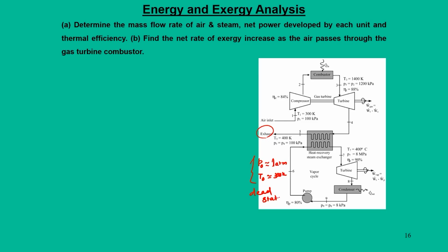Now, when you perform this exergy analysis, the picture will be clearer. To do that, first we need to find out where the points of entry for exergy into the system are, where the points of exergy going out are, and where the points are where exergy is lost.